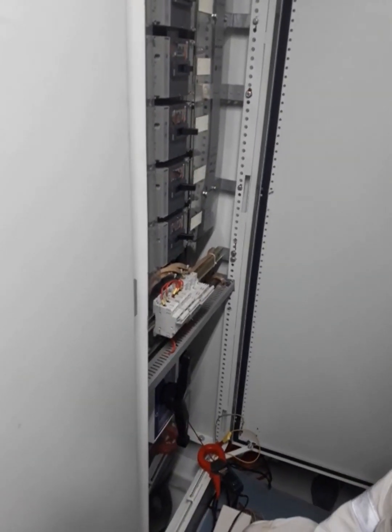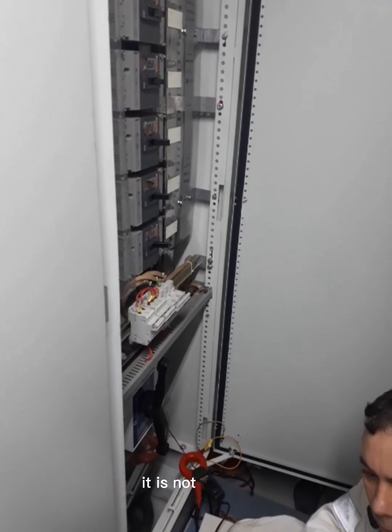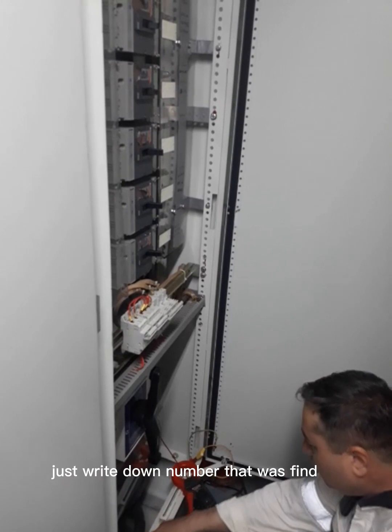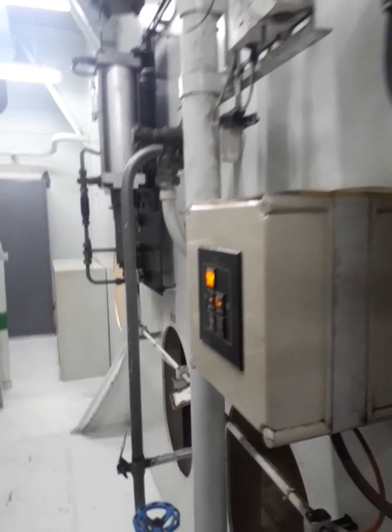For example, for engine control or valve marine control, we just do not shut down if it's not possible. If the ship is running, we just write down the number where the ground was found, and when it's possible, we come back and we do the shut down.